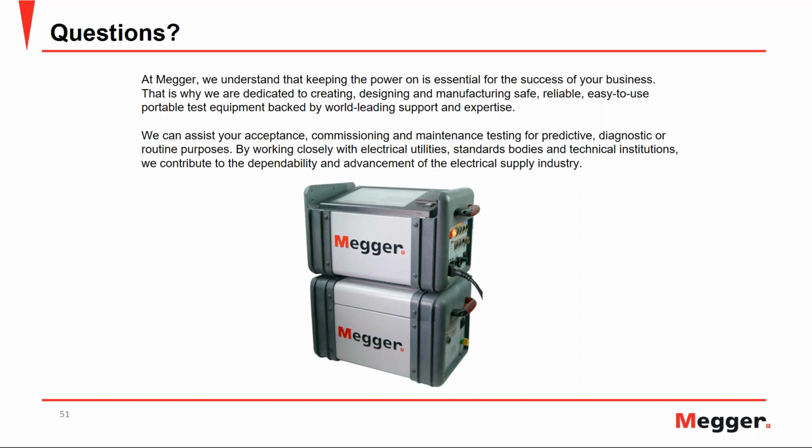Thank you, Charles. Daniel, is there a benefit to do power factor testing on dry type or resin cast transformers? Sure. Okay, this is a good question. It's very commonly asked during this type of conversations and trainings about power factor testing. And the short answer is yes, right? Obviously, you don't have that liquid part of the insulation, but you can still perform the test following the rules for voltage to test. And again, you can trend those values over time to assess how the insulation is evolving or is aging through the life of the transformer.